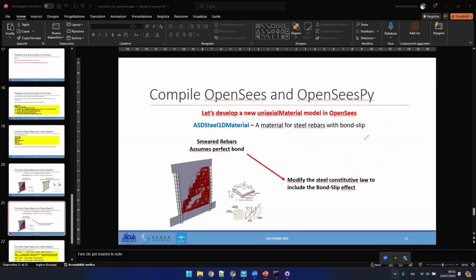So just to recall a little bit the concept of slip. When they do tests on slip, they put a rebar, which has a sufficient anchorage length, inside a piece of concrete, okay? So they put a force here. They measure the displacement of the rebar with respect to the concrete. So this one is going to be the slip of the rebar with respect to the concrete.